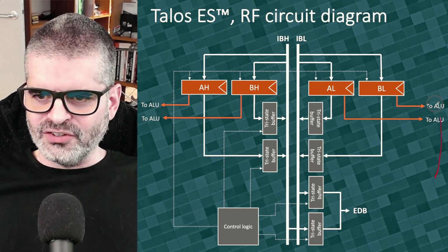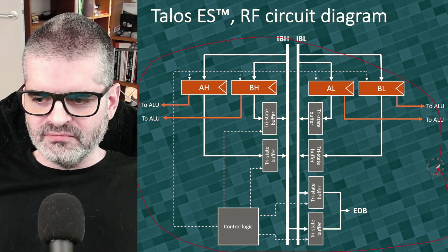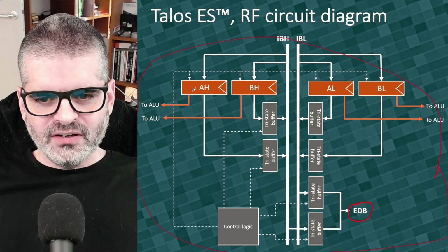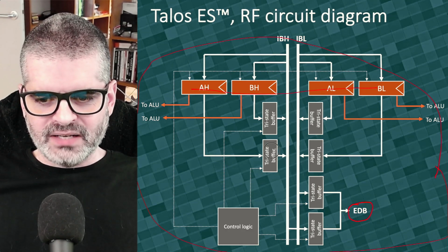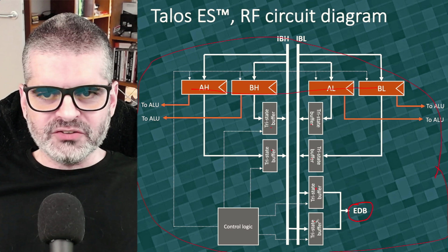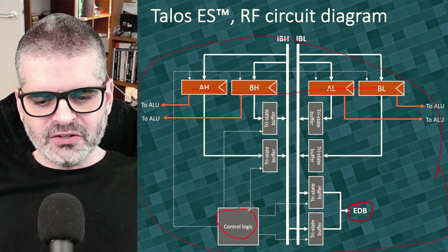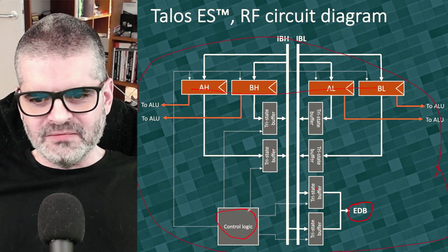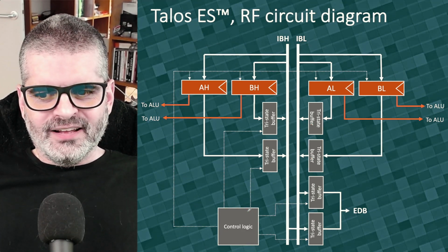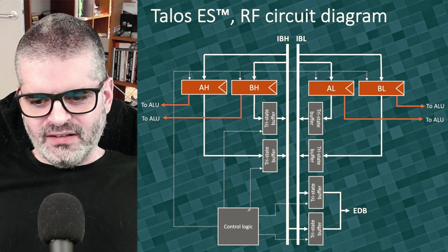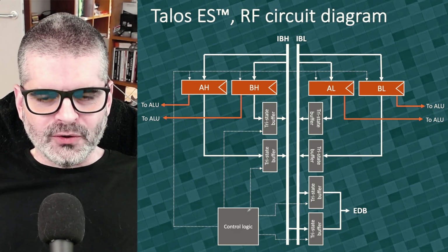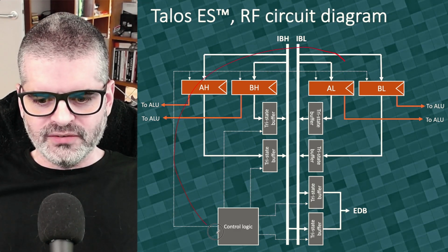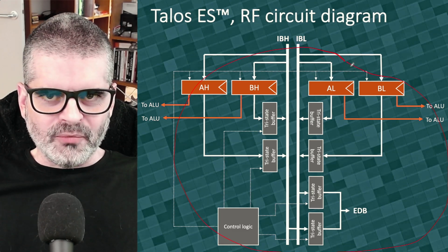The design itself is just this simple: a 16-bit internal bus, an 8-bit external bus, 4 registers, the respective tri-state buffers to deal with bus contention, and a little control logic to make sure that the load enables and output enables are turned on and off correctly. That's it. Let's move now to the first bare bones model in Logisim, the simulator, where we basically transfer this into the actual components in the simulator.